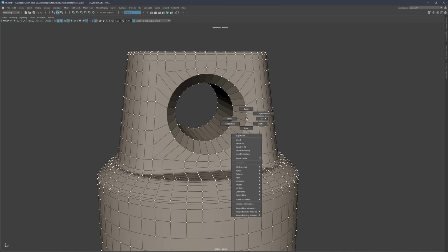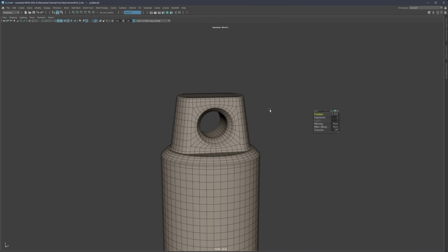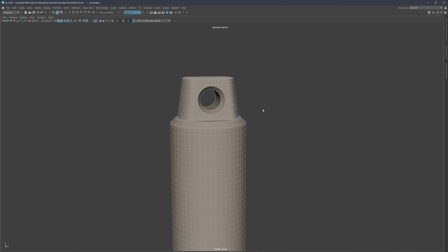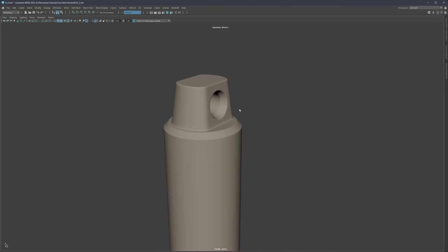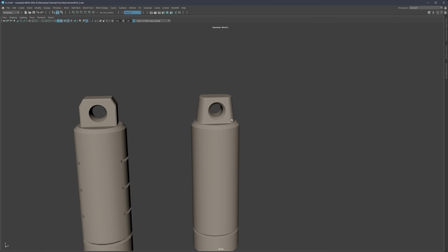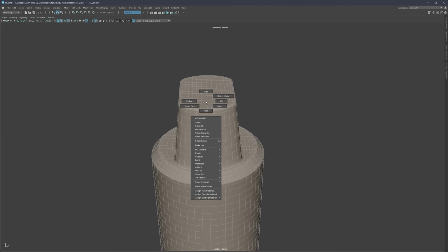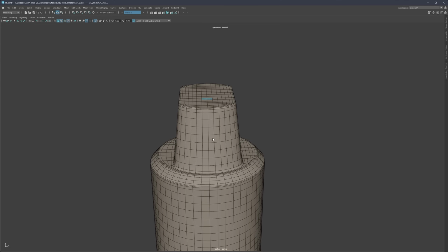But okay, let's go to edge mode. So select these and again, then just bevel edge, chamfer off, and give it enough fraction. Q to confirm, object mode, and with switching between 1 and 3 hotkey, we are just previewing how everything is looking so far. And there we go. Okay, let's now continue. Now we can do the detail, let's say here on the side that we wanted.